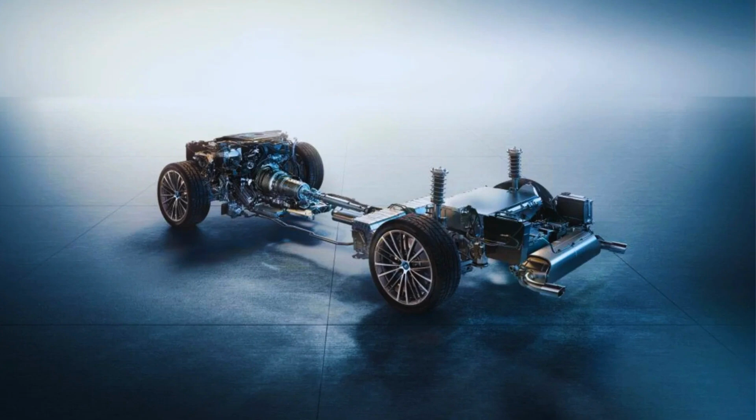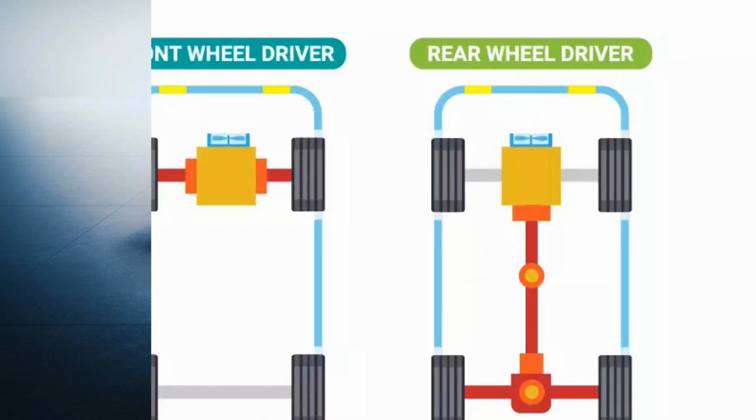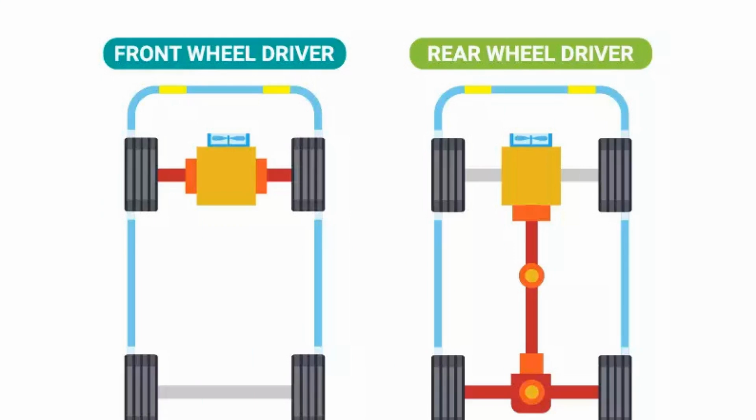The need to reduce the volume of cabin space. The so-called salon tunnel is designed to accommodate the cardan shaft under the bottom. Increase in weight and mechanical losses, which is facilitated by the presence of a cardan gear and differential. Rear-wheel drive has poor cross-country ability, since the rear axle is not loaded. Therefore, it is more difficult for the drive wheels to move the front axle.